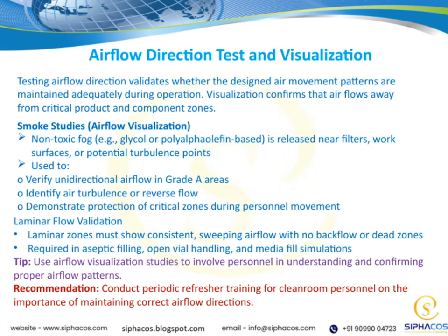These studies serve several purposes. They verify unidirectional airflow in Grade A areas, identify any turbulence or reverse flows, and demonstrate how critical zones are protected during personnel movements. Using smoke studies, we can see exactly how air behaves, ensuring that our airflow patterns are functioning as intended. This helps us confirm that the environment remains sterile and that the airflow is effectively directing contaminants away from critical zones. Overall, these visualization techniques are invaluable tools for validating and maintaining the integrity of our cleanroom